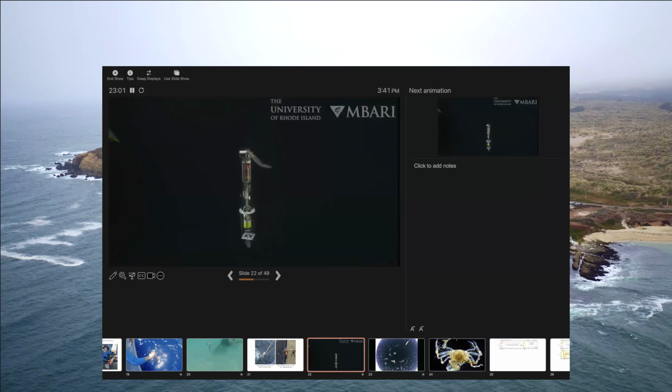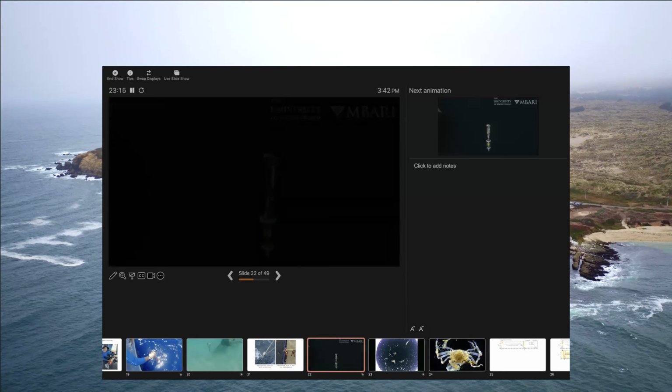When we were at what I thought was the target depth, it would open up and release the float, and then we were able to follow after it. This was really nice because we could see the whole life cycle, including how it drops the weight, which uses what's called a burn wire, basically electrolytic corrosion, to release a little bit of monofilament that then drops the weight off the bottom.